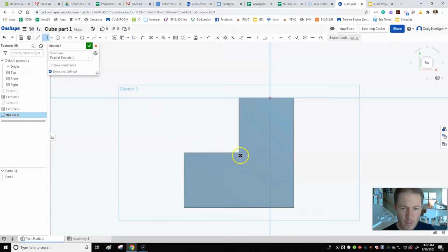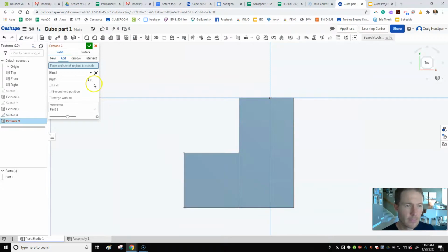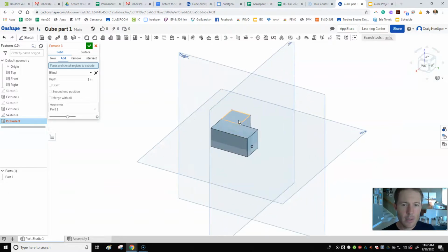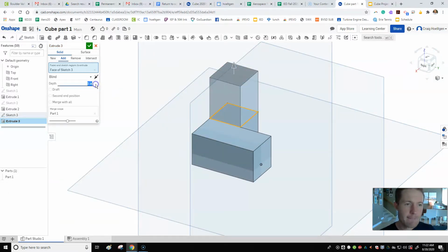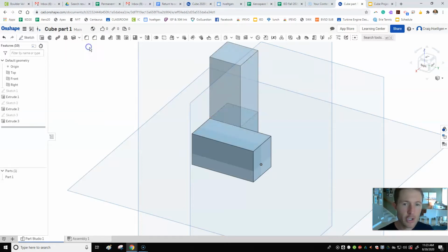A rectangle. And I selected that corner, bring it down. That's awesome. It locked into this other corner for me. That's going to save me the need to do dimensions on it because I went from this corner and it locked into that corner, kind of snapped in is what it's called. And now I can just extrude that right away. Let's go extrude this. And let's see, how far do we want that? I'm going to tilt it so we can see this a little bit better. We want this to extrude, let's say two blocks. So I'm going to say 2 times 0.75. Or if that's easy for you, you can just type in 1.5, enter, and check.